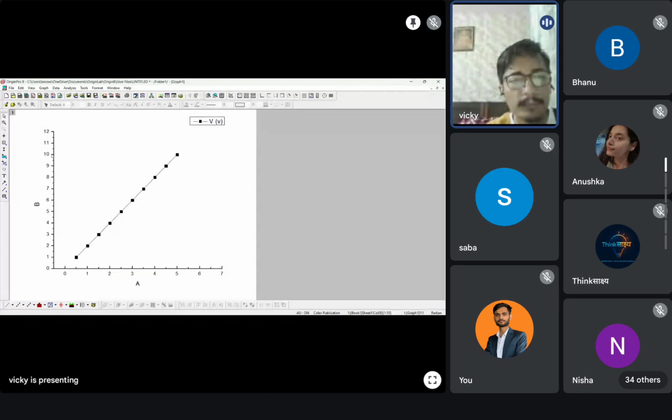Similarly, I can do the same for y. I just click it, go to minor and major tick labels, select in here, and then click OK. So you can see on the y-axis also all the ticks are now inside, right?